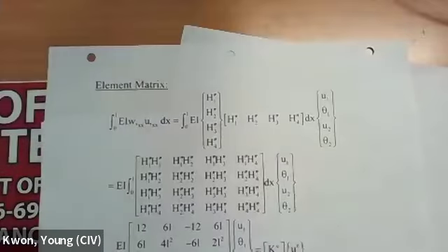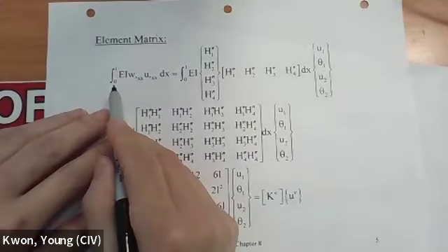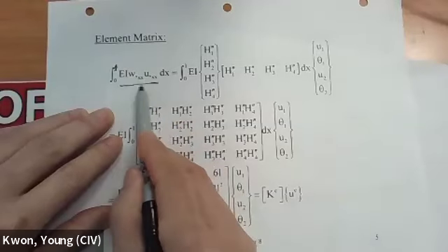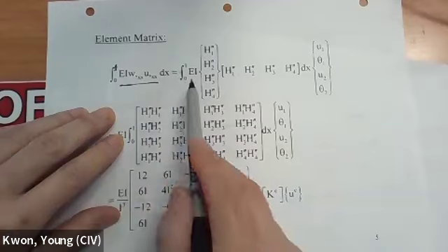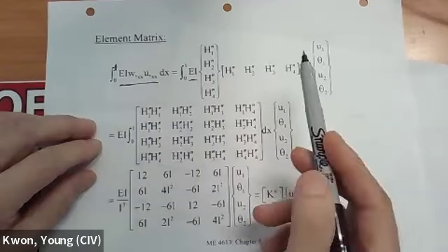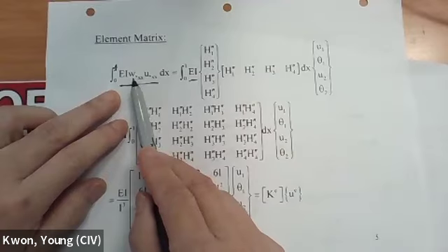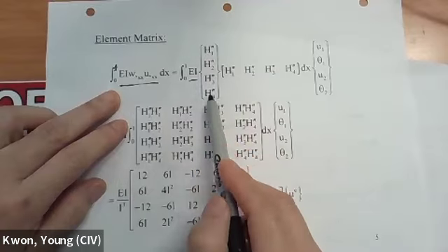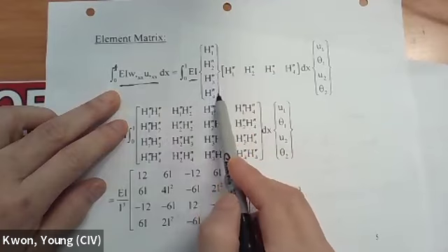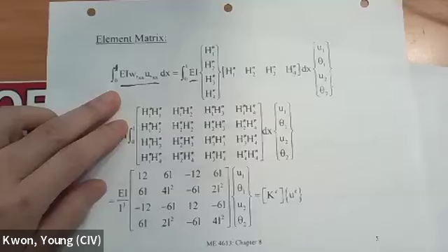let's evaluate element matrix. So element matrix, let's say element is from 0 to L, lowercase l. This, right, from the previous formulation. So EI mostly constant. Again, if EI is a function of X, it doesn't matter; this can be a function of X. So in Galerkin's technique, W is going to be also equal to shape function H1, H2, H3, H4, and comma XX means that's second derivative. And also U is going to be second derivative multiplied by this one, right?